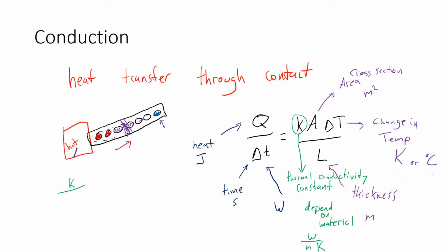So for wood, if you want the K for wood, it's going to equal 0.16, thereabouts. And there's lots of different types of wood. These are hardwoods, woods that you would use in buildings or whatever. So if you want for concrete, so, you know, stone, concrete, that kind of stuff, that's going to be 1.7.